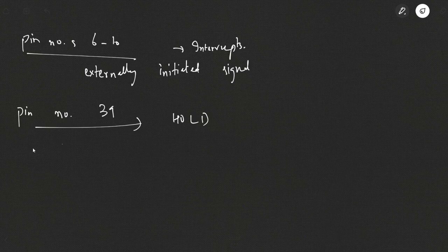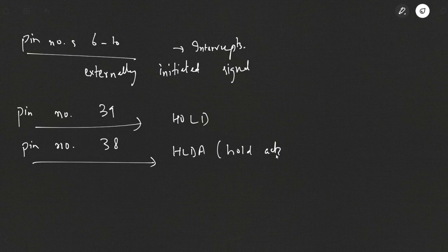Associated with this is also pin number 38, HLDA. HLDA is hold acknowledge. Again, this is an externally initiated signal. This signal basically acknowledges the hold request.